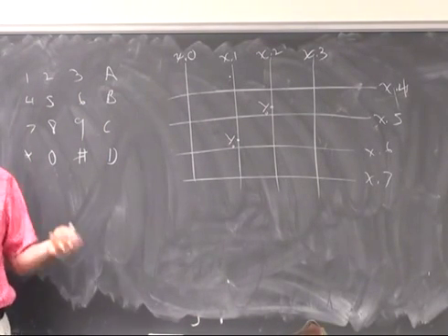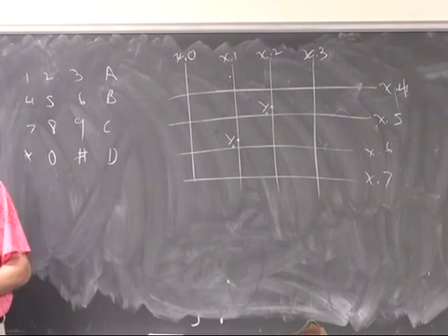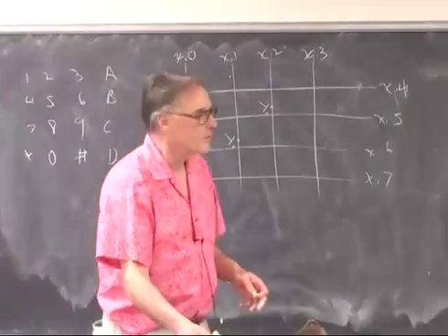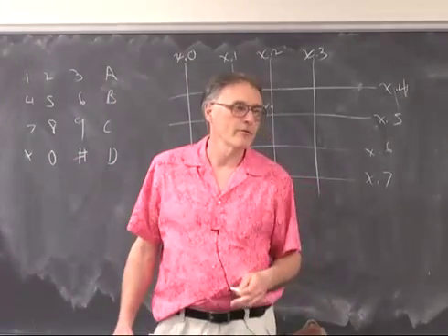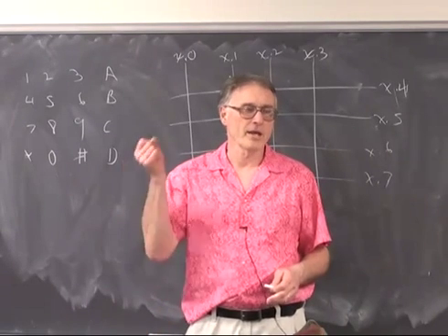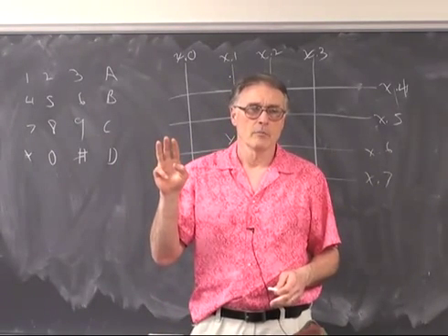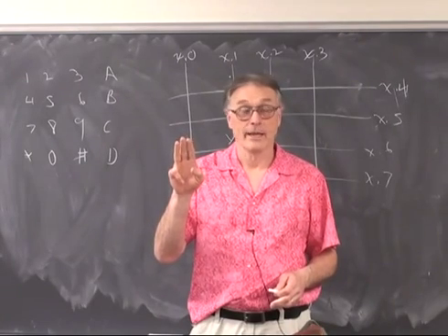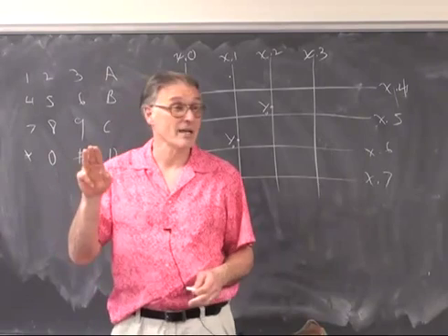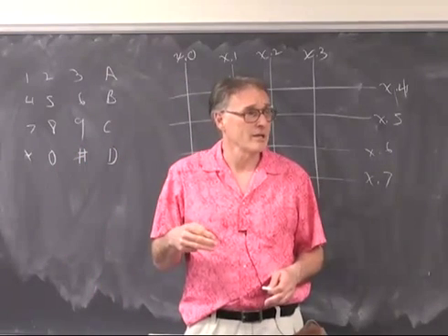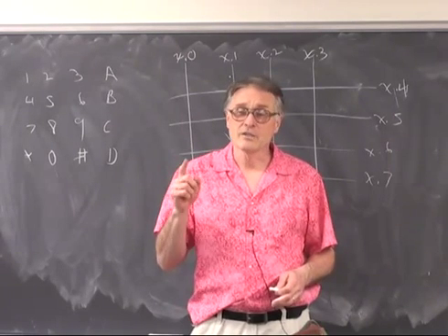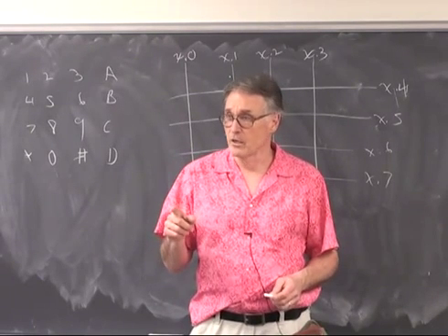So any button connects one vertical wire with one horizontal wire. Now I've bought keypads at 3 different times, and every one of them has a different pinout. So there are 3 kinds of pinouts: pinouts at the top, 8 pins; pinouts at the top, 9 pins; and pinouts at the bottom, 8 pins. The 9th pin changes state if any button is closed.